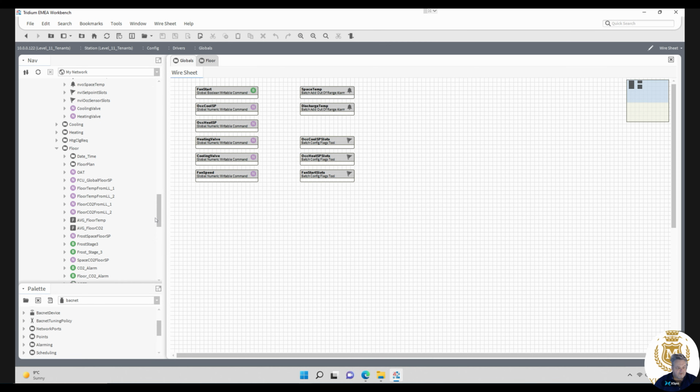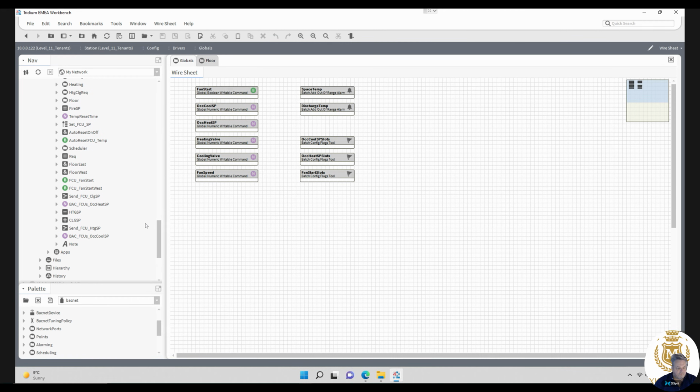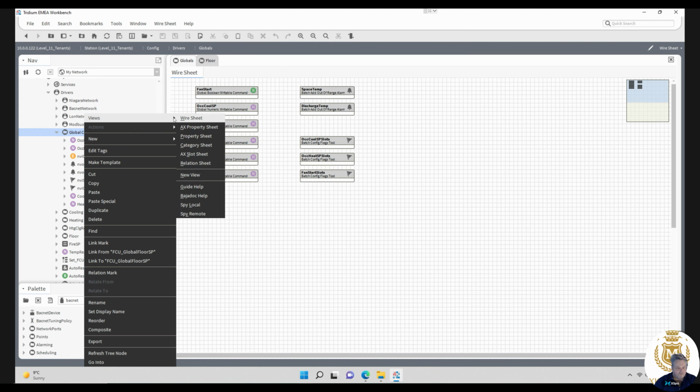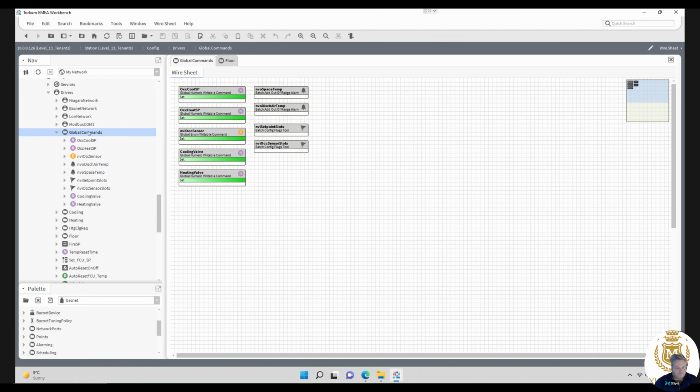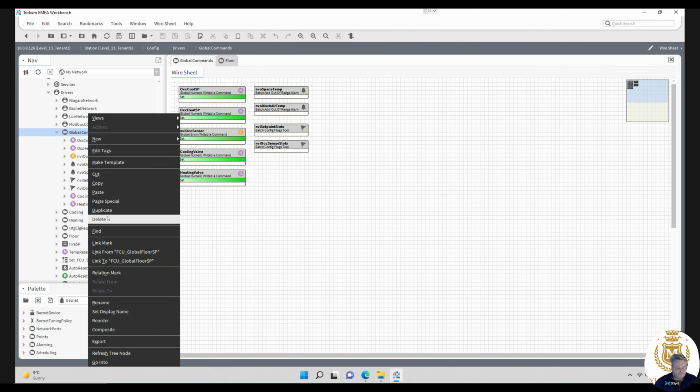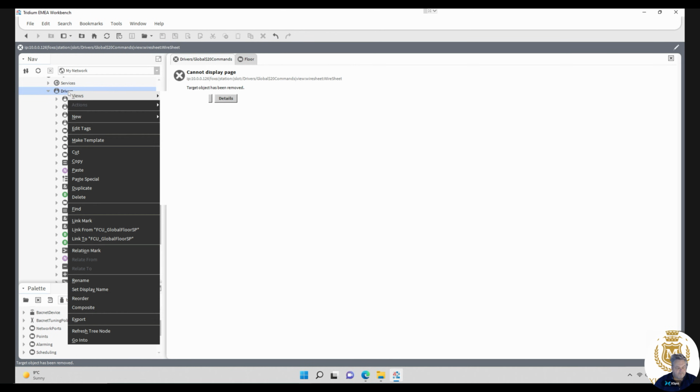And then on level 13, where we've got globals somewhere, that's floor, globals. Again, there shouldn't be any links, which there isn't, so we can delete that, paste in that.